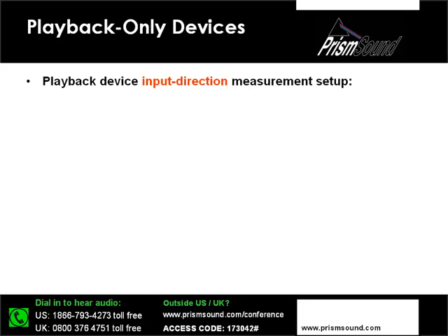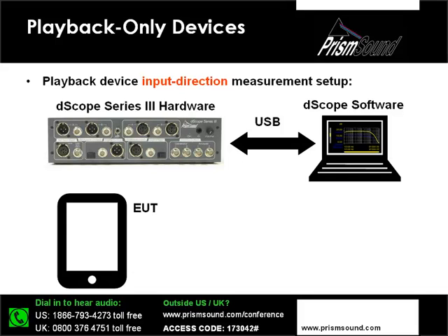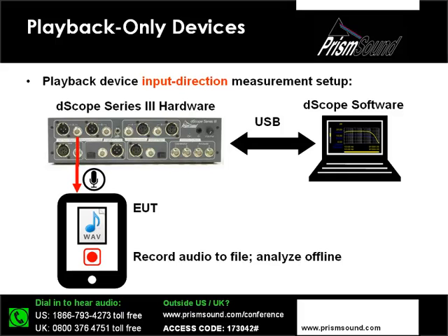What about the input direction? Well, there are many devices, tablets, laptops, smartphones, etc., which may have inputs, and in particular systems that are designed to handle voice, so microphone inputs are quite common on these types of devices. How would we go about testing a mic input? Well, ordinarily you could use a loop-through test, but perhaps not for this type of device. On my tablet, what I would do would be to connect a signal from the test system's generator to the mic input and then record an audio file which can then be analysed offline. So that's the basic idea.